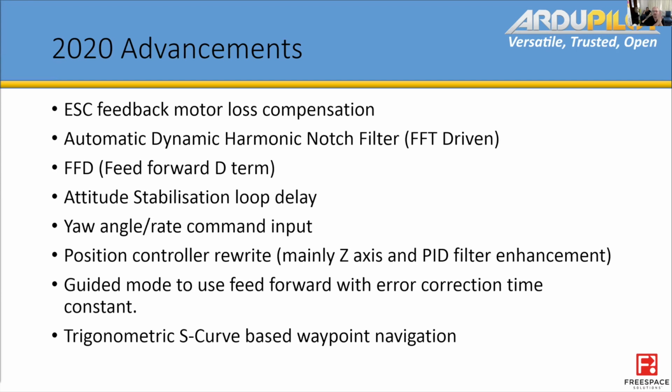And so this allows us to actually feed a rate and a target angle into the yaw controller, and the target angle stays precisely on the actual measured angle, because you're also feeding this rate in there, until the rate exceeds your maximum rate, in which case you hit the limits, and those two things come apart, because the attitude controller can't maintain your target rate.